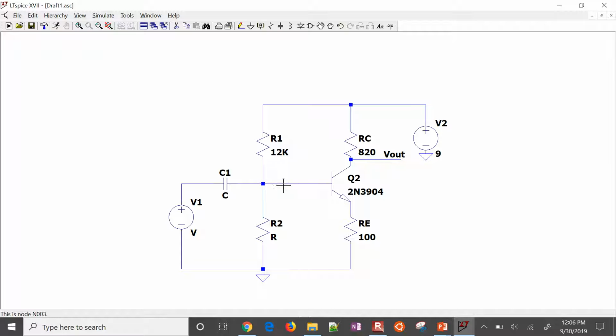And what we're trying to do is have the right amount of voltage or current coming through here, and then that will amplify, and there's going to be a current coming through here that's going to make this sit about 5 volts. So this is a bit convoluted. If you're biasing a common collector amplifier, it's much more straightforward. The common emitters, you're controlling this voltage to control this current to get this to sit at 5 volts, and it's a little bit of a pain. But I don't mind if you use LTSpice as a design tool.